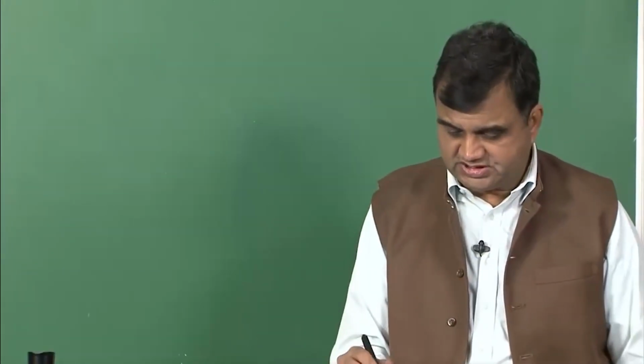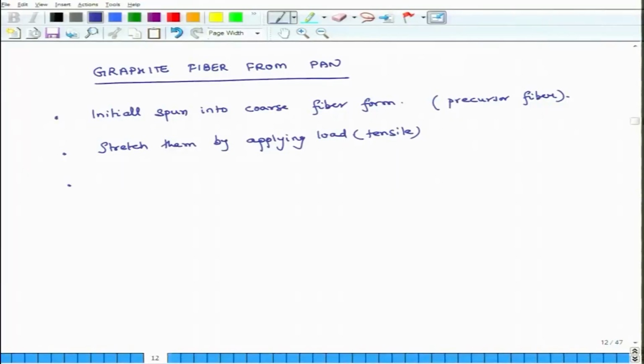And while you are stretching, you also simultaneously apply heat. How much heat? 200 to 240 degrees C for 24 hours.